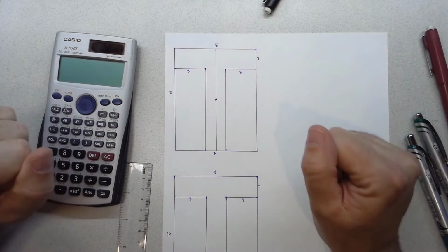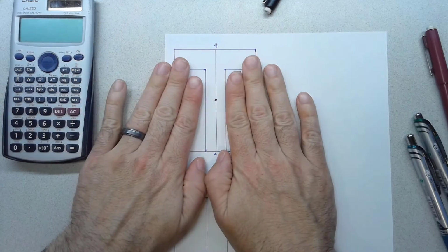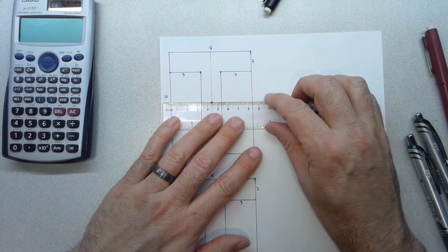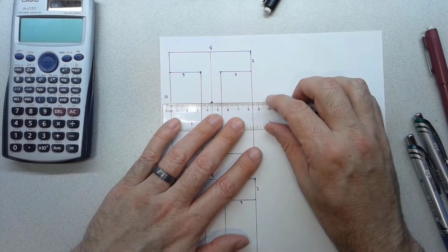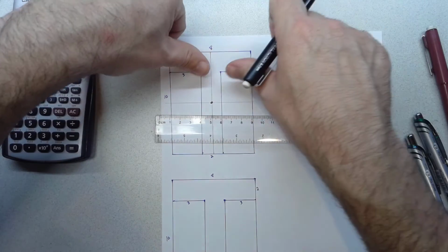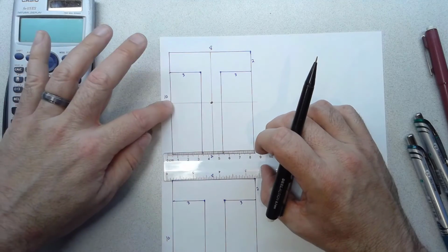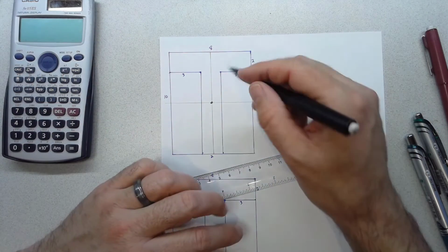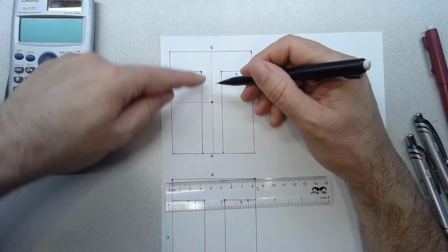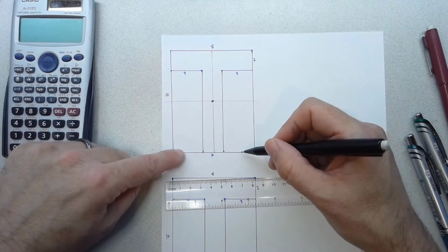What's different about this as opposed to the I shape is that the final composite shape, the T, has a centroid that is not located along that same neutral axis. If this is the neutral axis for the big rectangle, because it's symmetric, the rectangle is symmetric about both this direction and this direction. The T shape is not symmetric. The big rectangle is, but the T shape isn't, right? If you mirrored the T around this line, we're missing these pieces down here.